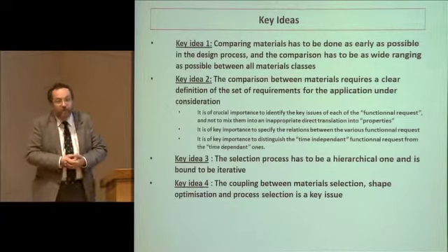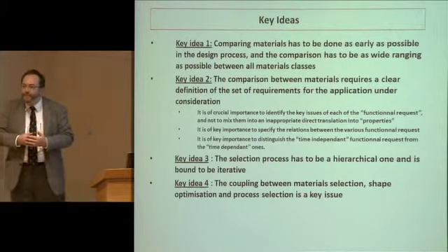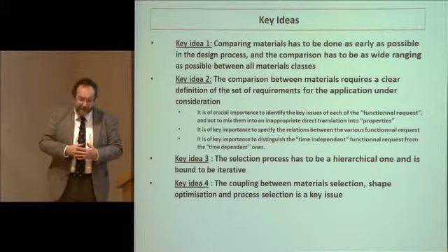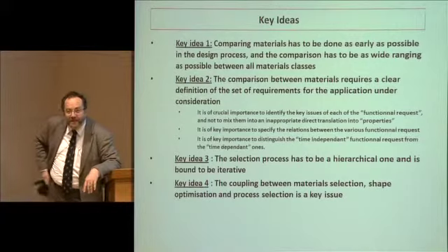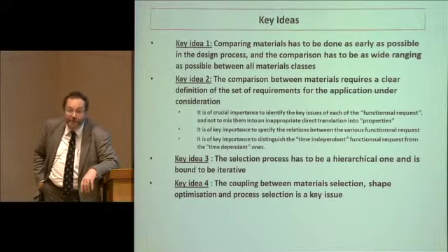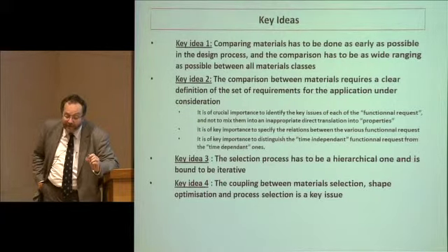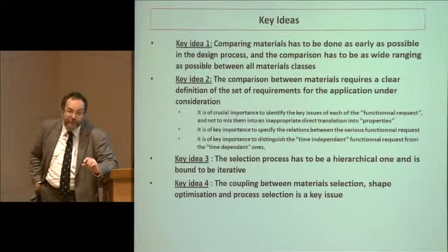The aluminium alloy wheel is much thicker and can be molded, can be cast. So then the question of, is it going to be heavier if it's steel or aluminium? If you look at the properties, you'll say it'll be lighter if it's made of aluminium. But if you look at the process, you will see that in fact you need to have much thicker parts.